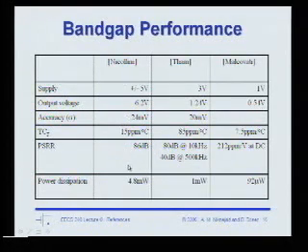So starting from this reference here, going to this more recent reference, interestingly enough, this more recent reference, using a less than 1 volt supply, generates an output voltage of 0.54 V, very accurate, about 7.5 ppm per degree C. Fortunately, these units are not the same as these units, so it's hard to compare the power supply rejection. But the power dissipation is very good, very low power dissipation, 100 microwatts.